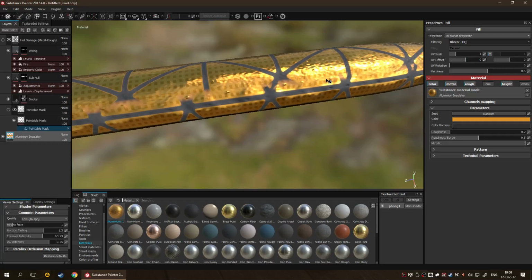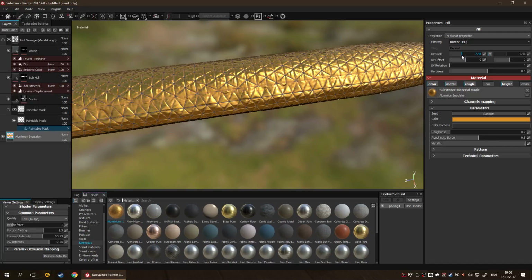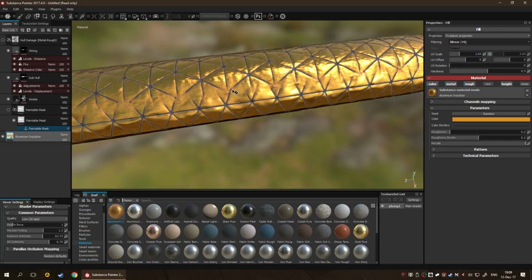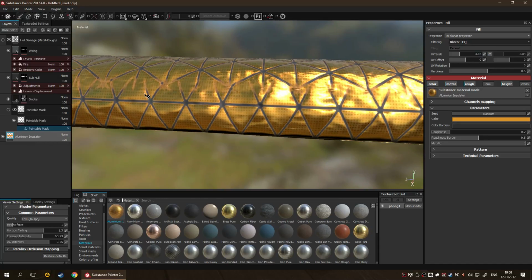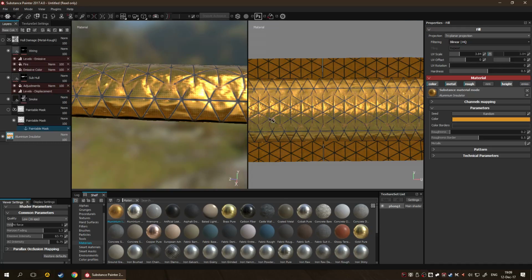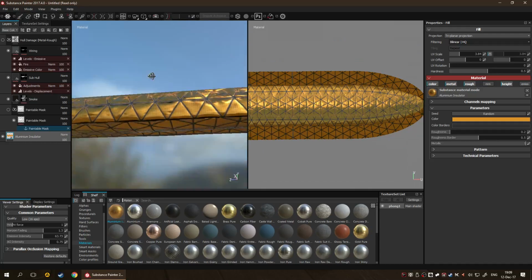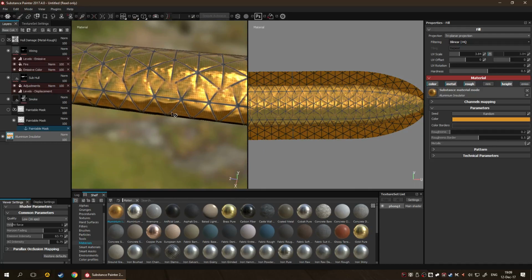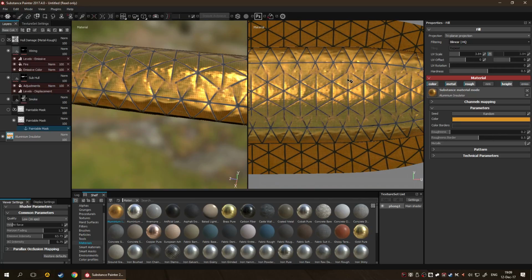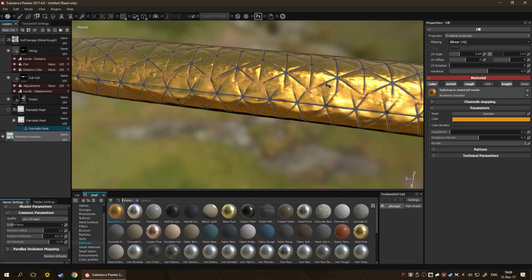The UV scale, by default I've set it to 1, but you might have it at 3. The scale is essentially how many times you've tiled the image. So in this case, I could tile it like this, right? For some reason, I do have a seam over here, so I really don't know. Does it have anything to do with the mask? No. Let's take a look here. Yes, we do have that problem since our UVs, again, are pretty bad. So we're going to be running into this issue fairly often. Well, actually, this does not have to happen. Maybe we have a very hard edge, and that's the way it works. But like I said, we'll try to bypass this in a minute.